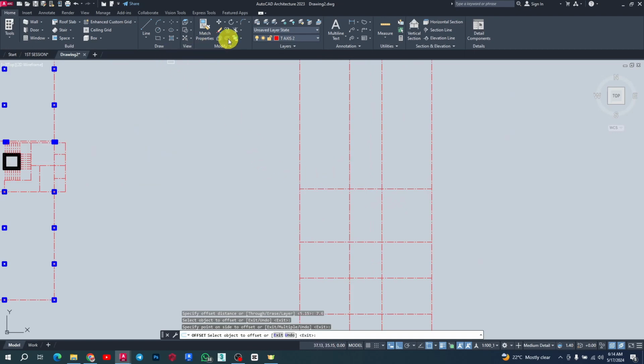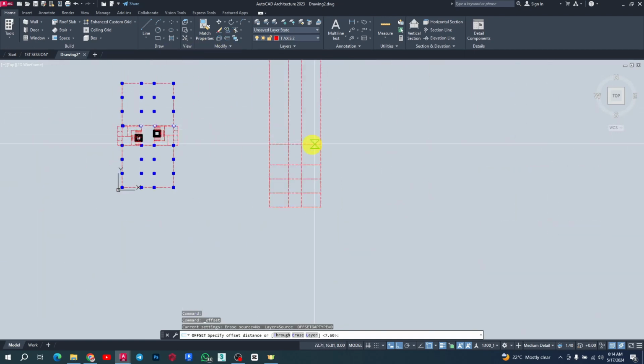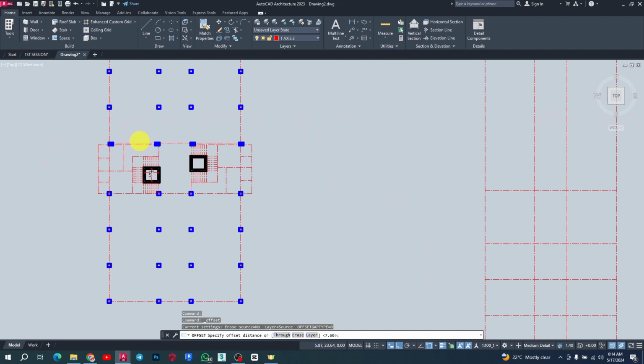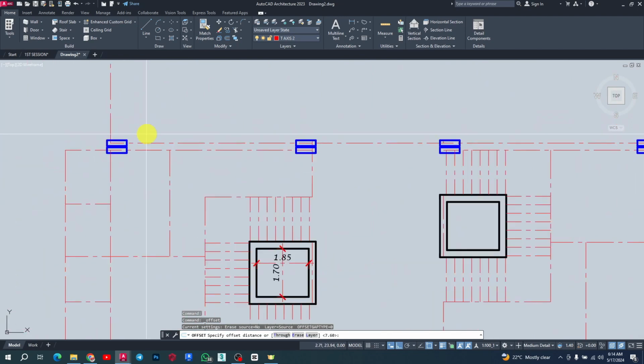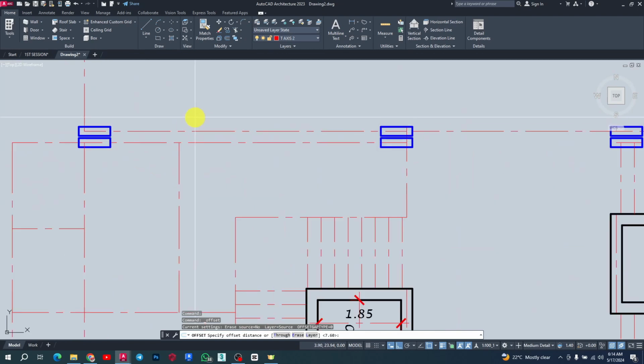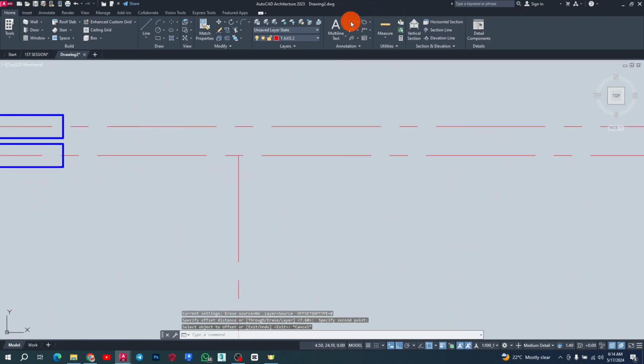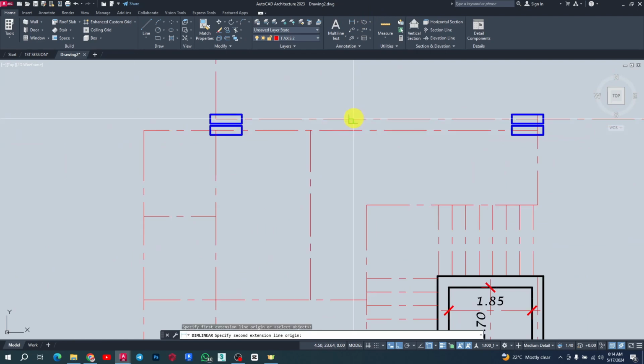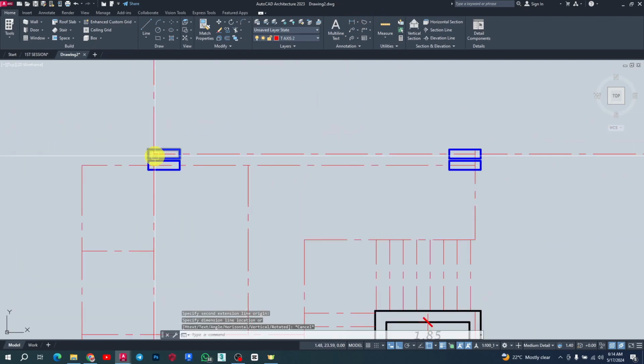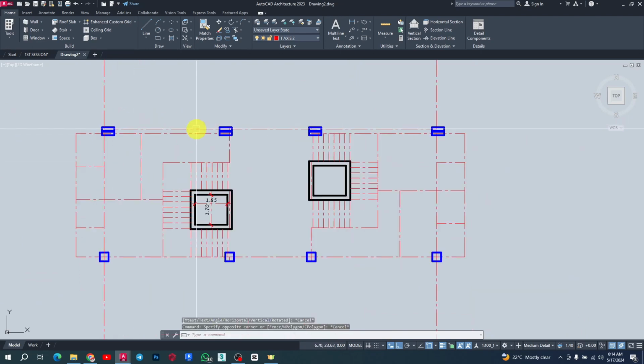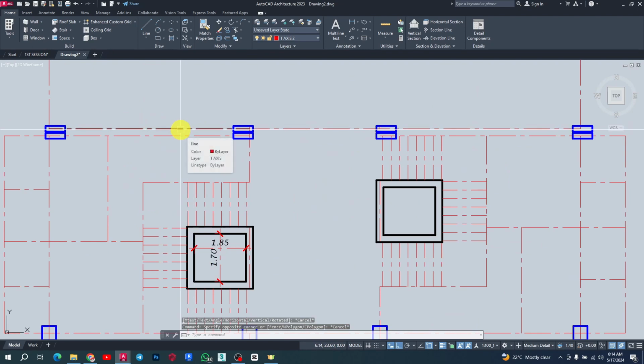And then now I go back to, since the length of the building is about 30 meters, it's necessary for you to always include an expansion joint. This is not usually common with architects, so they might not really have this in mind while working. So working as a structural engineer, also as a draftsman or architect, gives you this flexibility to be able to understand the structural functionality and also consider everything that you want to include in your drawing, right?